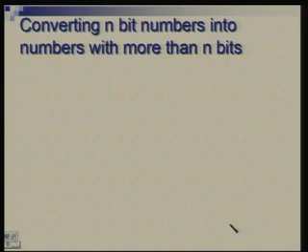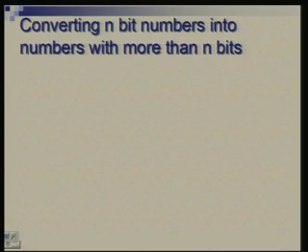Okay, there is one additional factor you need to keep in mind, that there are some instructions, for example add immediate, which require one operand to be 16 bits and one is 32 bits. So how do we perform addition or subtraction with one large integer, one small integer? The hardware inside the processor would be common for the add instruction or add immediate instruction, okay.